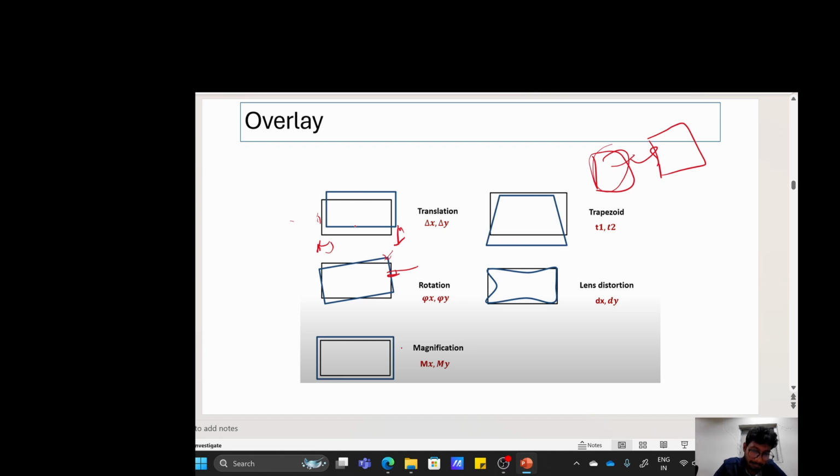Okay, there is a magnification. Magnification comes in projection lithography only. Let us say the feature size in the mask is 2 micron, and the magnification is 4 times, so you would like to get 500 nanometers through that mask.